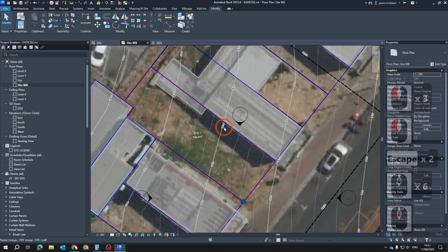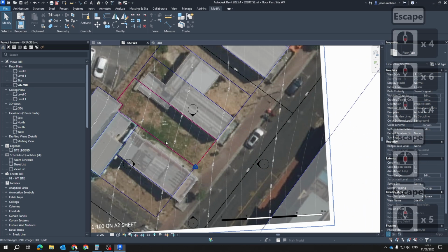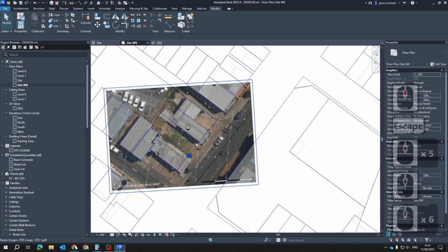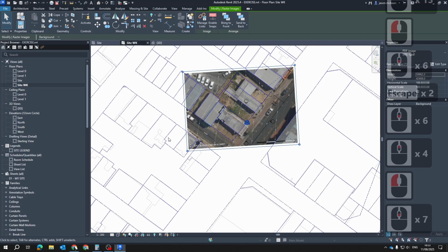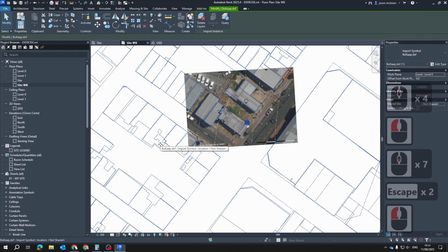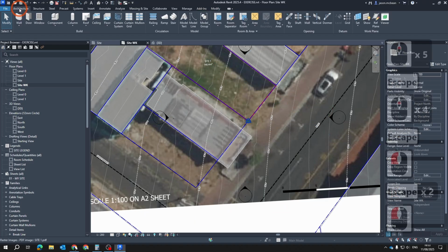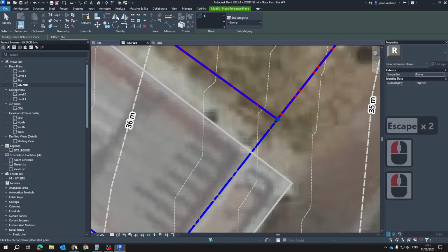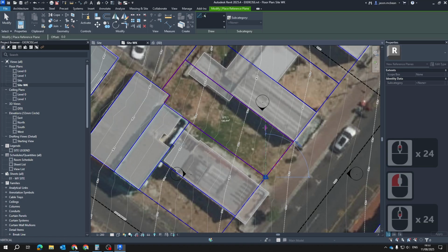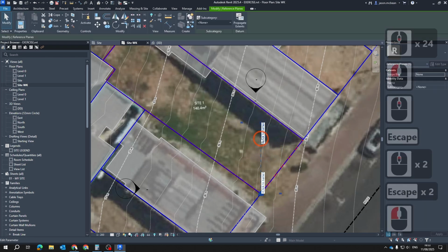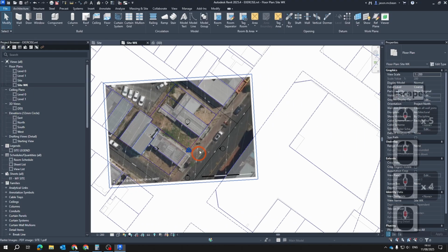Okay, good. All right, so I've kind of got the project started and going, but now you will notice that the site true north is going to be, so as per the image, I know the image is strictly not 100% correct, but I know that this is correct. And I know that true north is always up. So I'm going to use a reference line. So in architecture, I'm going to use a reference plane to help me sort this out. So I know that this angle, that's true north. Okay. Now with Revit, this is something that I think a lot of you should understand before.